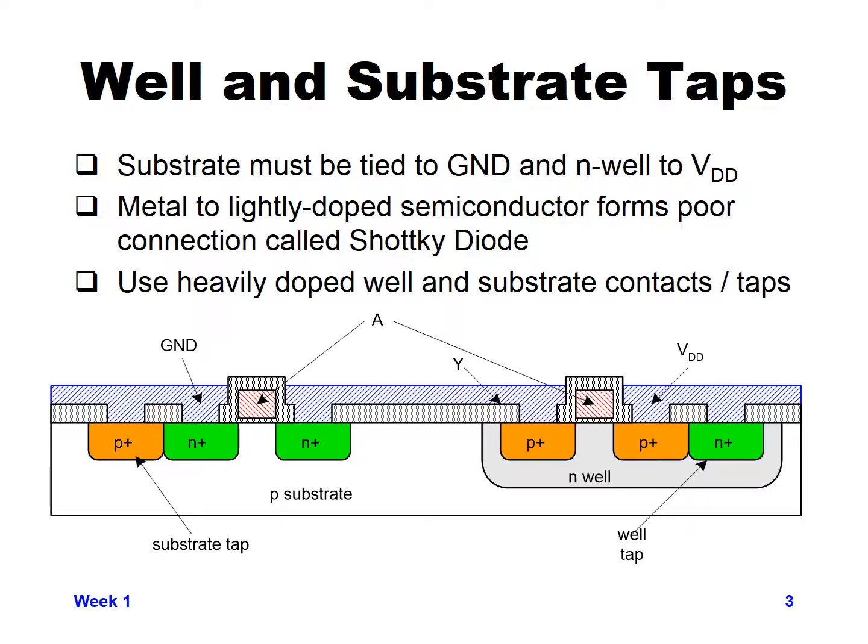So it will be connected to the same metal ground connection. And then for our P-type transistor, which has an N body, which is the N well, we need a connection to the N well. So the connection to the N well will have to be an N plus type material so that it connects well to the metal, and that has to be diffused into the N well.